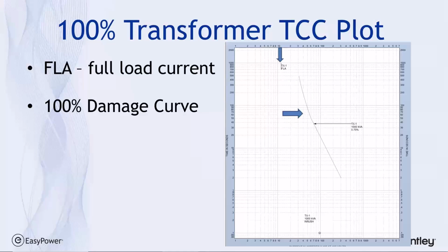Lindy's asking the question, should we calculate arc flash incident energy for both upstream and downstream of the transformer? Well, frankly, the answer depends upon whether you're going to have workers in the area. The requirement of NFPA 70E, rather than IEEE 1584, is if anyone's going to be in the area, then their exposure to arc flash needs to be calculated. So it depends on your situation.